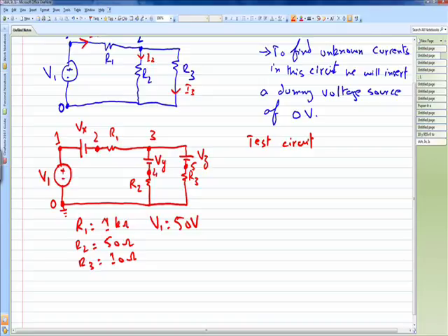So in sequence, let us first define all the voltage sources that are connected in this circuit. V1 is connected between, we will be using a space here, because we cannot just combine things, we will be writing V1 space first node space second node, because this V1 is connected between node 1 and 0. Since 1 is connected with the positive terminal, we have 1 first and then 0 second. And then we will add a space.